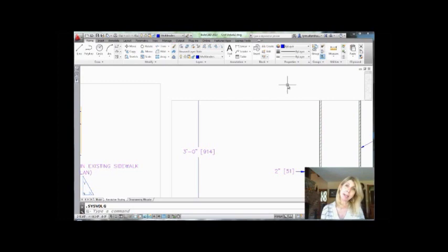Today we're going to be talking about a great Express tool. You know how I love my Express tools. And this one's going to help us control and set our system variables. Now you know there's about 1 zillion, maybe a little less than 1 zillion system variables inside of AutoCAD. And this particular tool is going to help us set those up and get them the way we want them to be, all right? Because it can get very confusing.